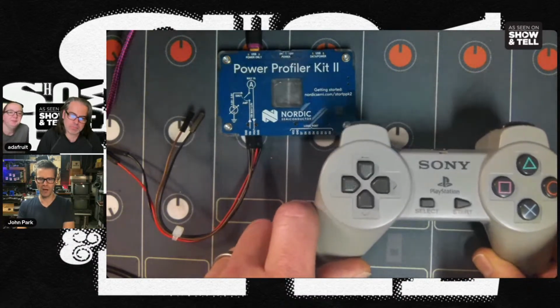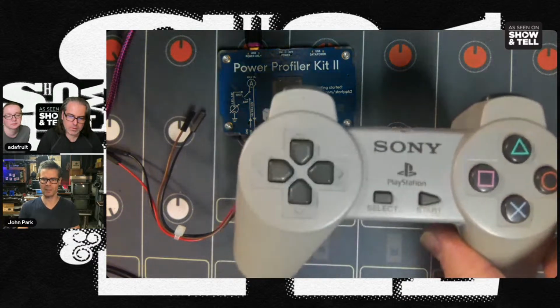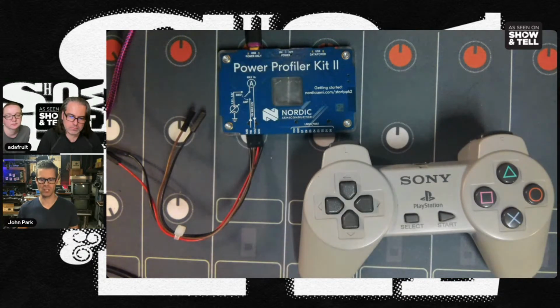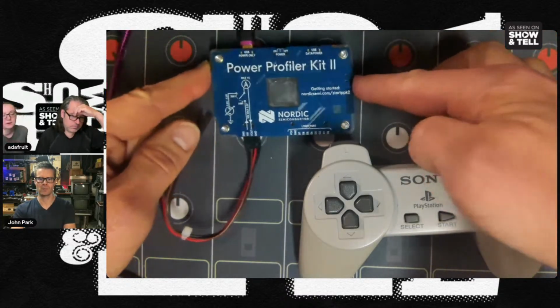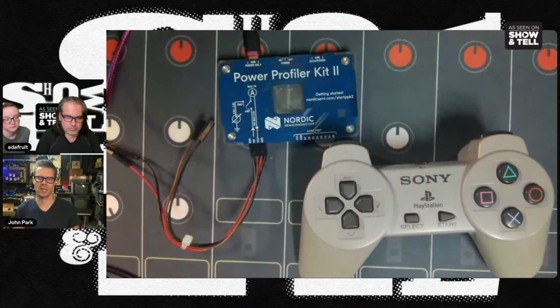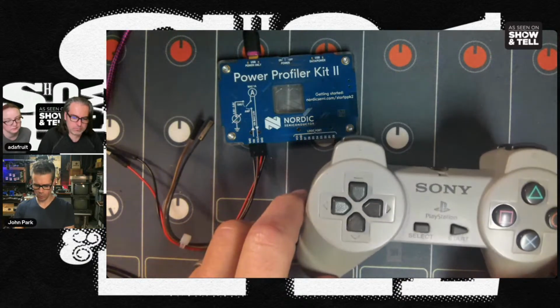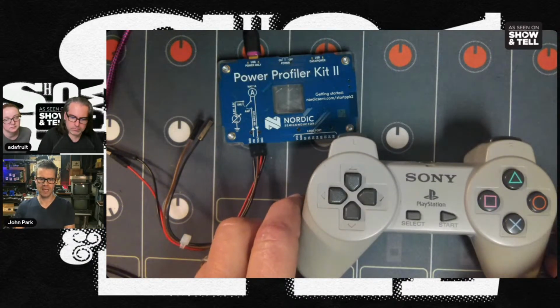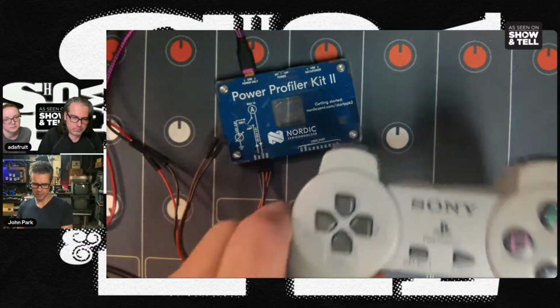One of the fun things I learned along the way was how to put it into deep sleep mode, and how to measure what I was actually drawing current-wise, because this is running off of a little LiPo battery, and make some changes to fix the whole thing. Limor said you can profile these really small currents really precisely with this power profile kit from Nordic, because a multimeter really wouldn't do you much good in this case. When this thing was in sleep mode, I was getting 1.8 milliamp draw. The way I knew that was that this was powering this instead of the battery.